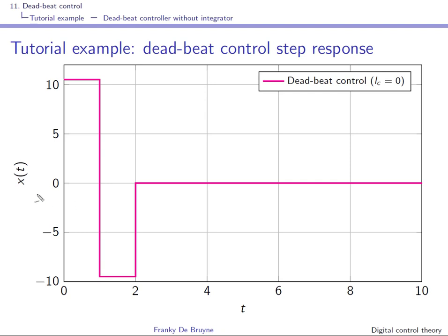You can see that the control energy comes to steady state after 2 sampling instances, and of course here this steady state is 0, right? Since we have to produce at the output a constant signal and you have an integrator in the process, this is kind of obvious.